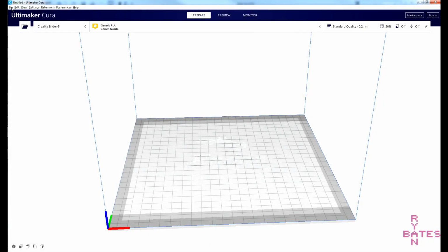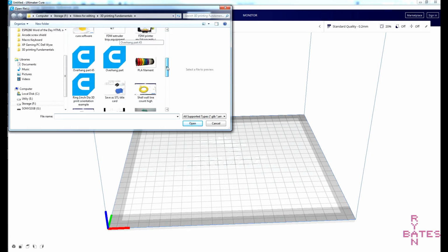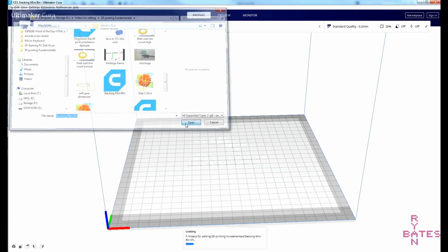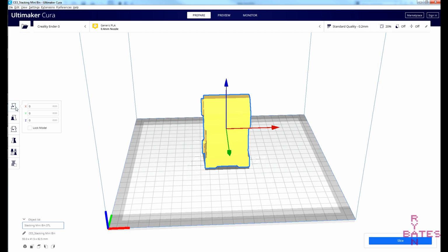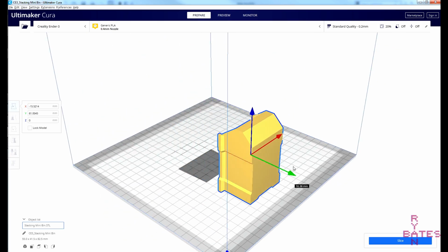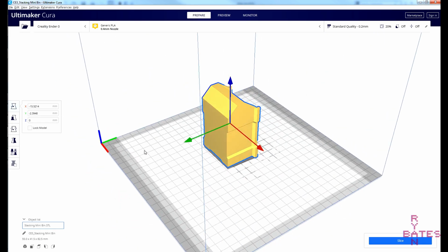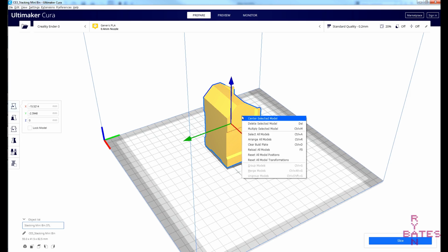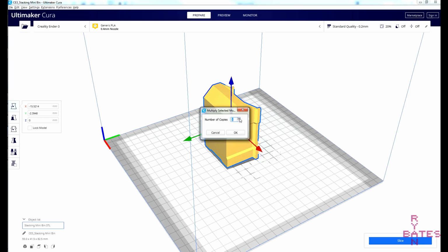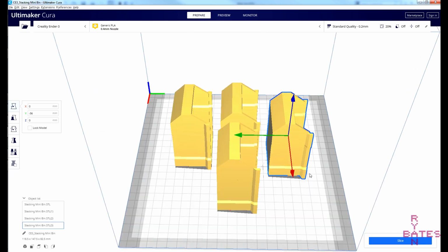With a basic STL or 3mf file, we'll move on to the slicer software Cura. To start, we will import a 3D model that we wish to print. You can move the model around the build plate. This might be necessary for large models where position affects printability, but printing in the default location is usually sufficient. If printing duplicate parts, do this by right-clicking on your model. Arranging your models with the Move command may be necessary. Note, for low-end consumer-grade printers, there's a higher chance of success when printing a single part at a time.